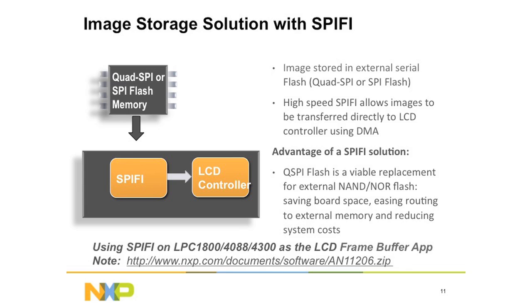And what it does is, through the SPIFI interface on the LPC4357, it takes the image or a picture directly from the flash and displays it onto the LCD controller with DMA. So what happens as a result is fast graphics. There's no load on the CPU, so you have enough bandwidth to do the others. And then again, it's a dual core, so you could actually use that for communication, the M0 for, say, loading a file via USB, doing some audio conversions on that side as well.